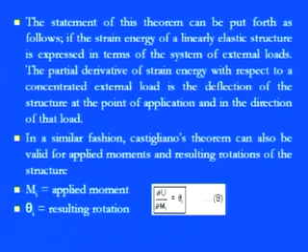Within those moments also we can say that the partial derivative of the strain energy with respect to the concentrated moment, not only the external load, will always give you the resultant rotation of the structure at the point of application and in the direction of the moment only.